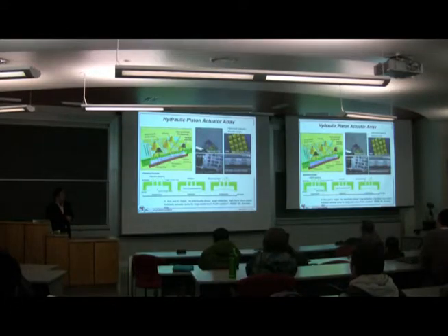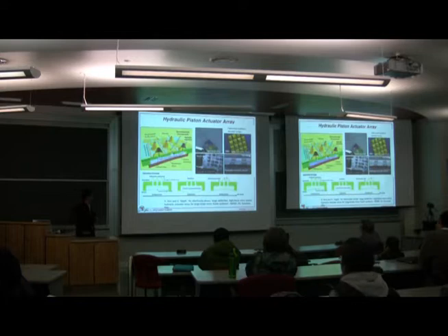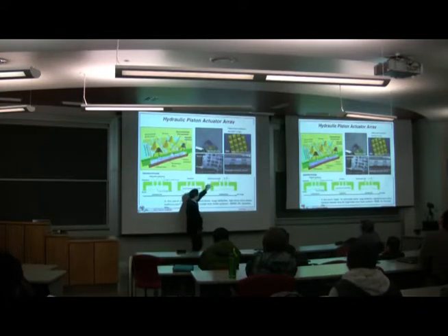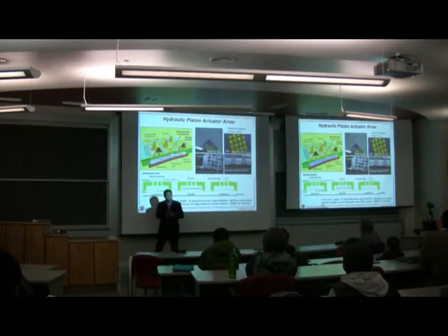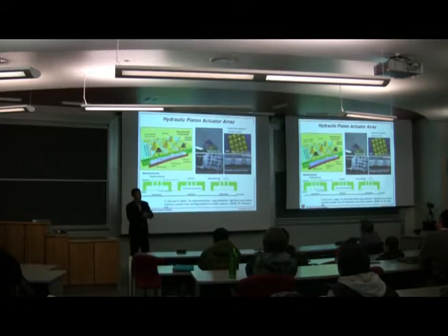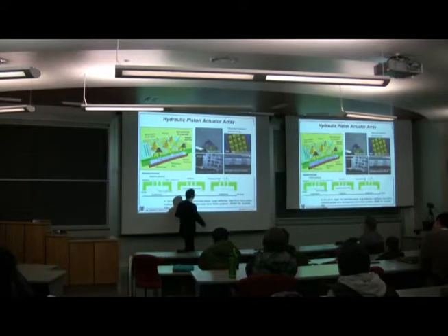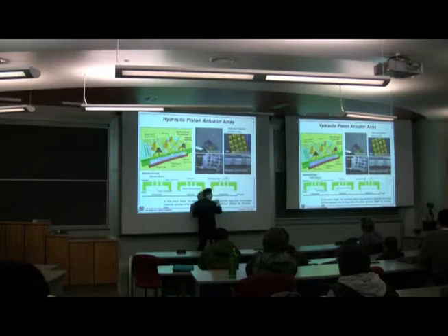They are meeting here. So if I apply 100 volts here, 0 volts here, and then when it is deflected, if I apply the voltage, then there is an electrostatic force, and then there will be electrostatic latching. So in the next cycle, this guy is latched down, but the rest of them come up.